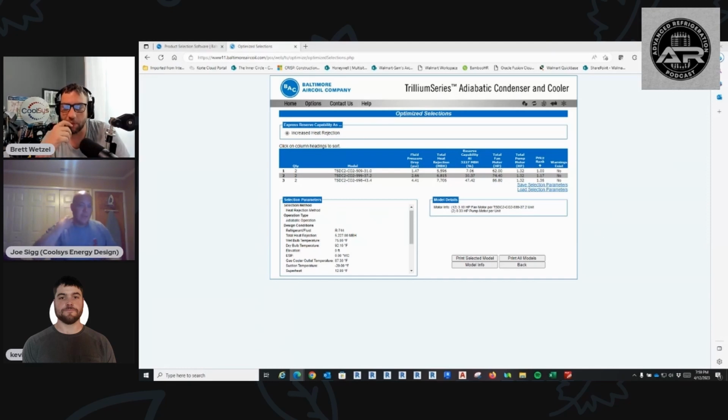Well, go ahead. One of the things that Kevin and I were talking about is if you could change your subcooling set point on your 326, your iPro. Typically most of these are set for 5 degrees of subcooling, right? Yep. Where if you would turn it down to 3 degrees, you're getting less subcooling, fine, but that's going to open up your HPV more, right? Which is going to put more pressure on your flash tank, which inadvertently would put more load on your medium temp. So you're robbing Peter to pay Paul, but I'd rather have the compressors have a solid load than not be as energy efficient as they could, because they're already falling on their face because of the load.